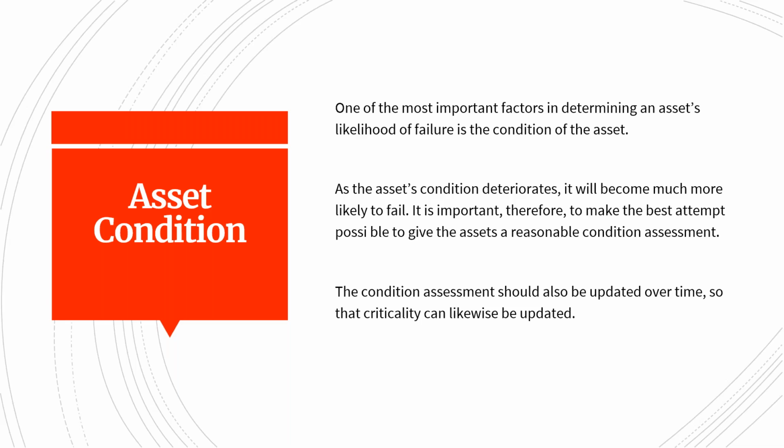Assets given a poor or fair condition rating are more likely to fail than those given an excellent or good rating. When the asset condition is combined with other factors, the utility can begin to make predictions regarding the likelihood of a given asset failing.